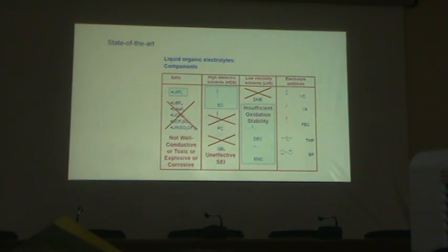So this was the last slide from yesterday, in which we figured out why we are using lithium hexafluorophosphate and EC, with some linear carbonates in a particular ratio. We figured out why that happens, and all the additives that we can use for different functions, like VC as an additive for both anode and cathode, FEC depending on the electrode we are using. These are all reactive additives. This is a co-solvent, and these two are basically our shut-off or shut-down additives that we use in batteries.